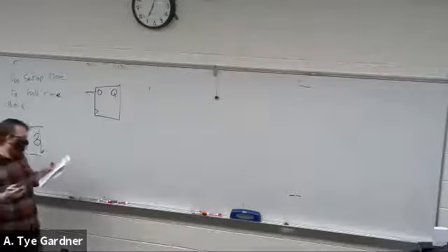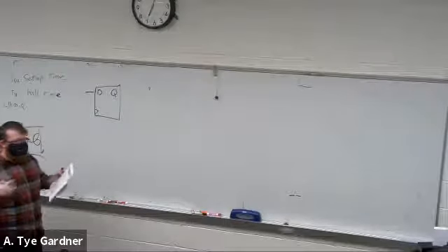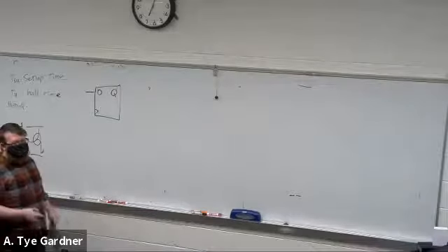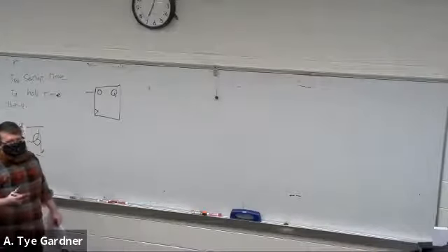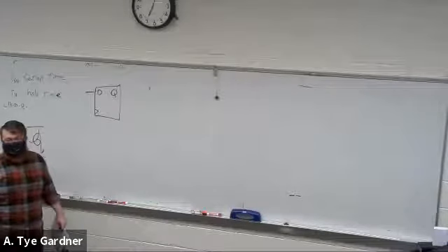That's all it's saying. Again, this is another way, if you don't meet setup and hold, of landing yourself in a metastable state, where it's going to be one or the other eventually, but you don't know when and you don't know what.